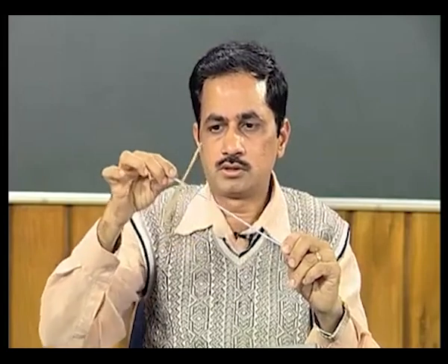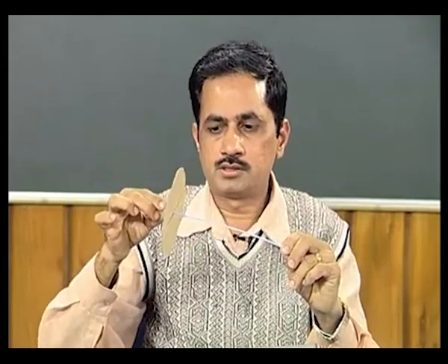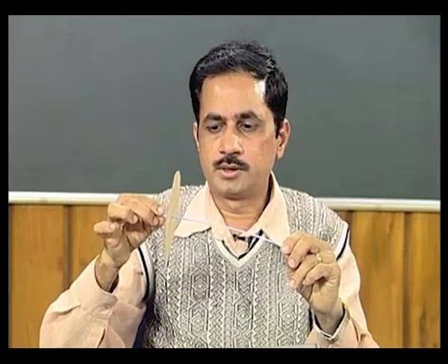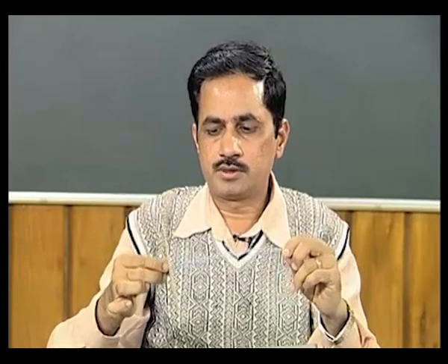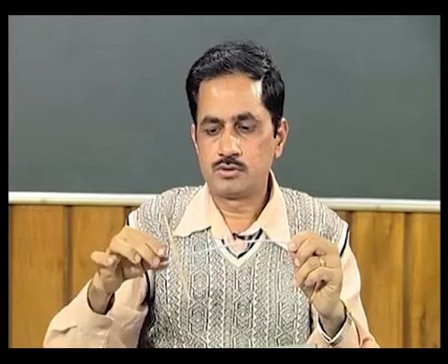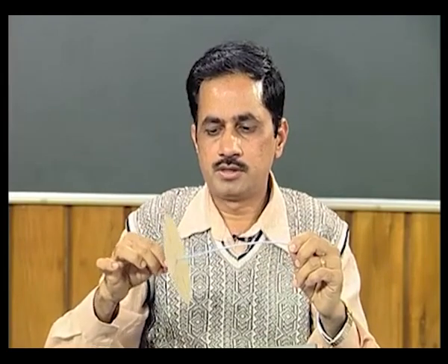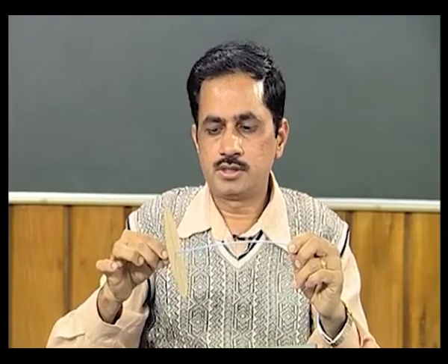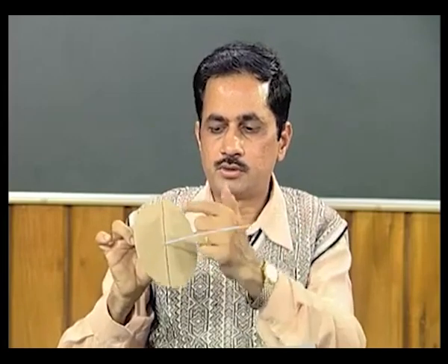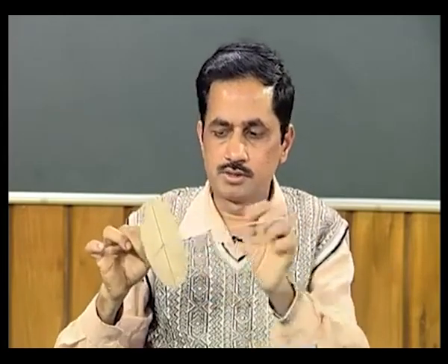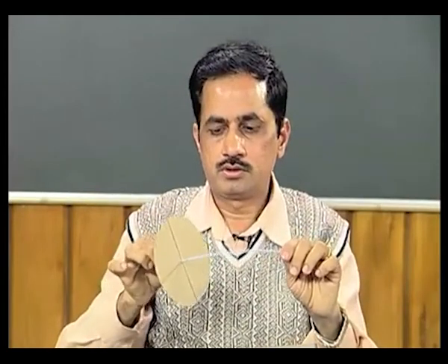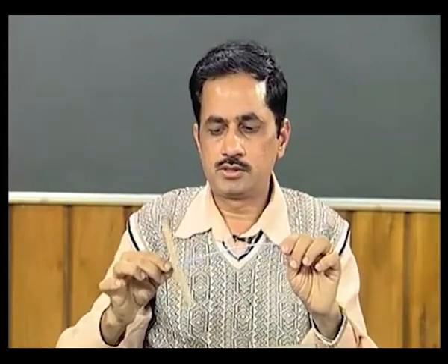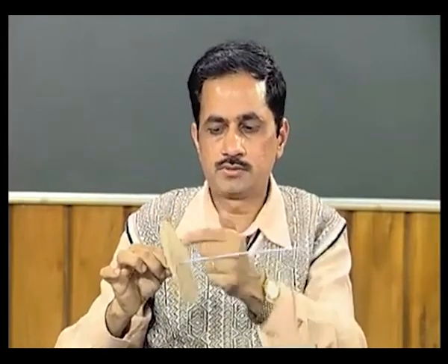So basically this particular disc is tilting about its diameter during the whirling, and now again we will consider, let us say, the bottommost position. When it is coming this side, you can see it is trying to tilt about this particular diameter, which is a vertical diameter. See, this is tilting at this particular instant about this diameter.